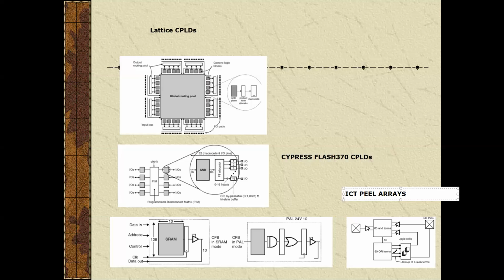It has a programmable AND plane that feeds a programmable OR plane. The outputs of the OR plane are divided into groups of 4, and each group gives input to one of the logic cells. The logic cells provide registers for the sum term and can feed the sum term back to the AND plane.